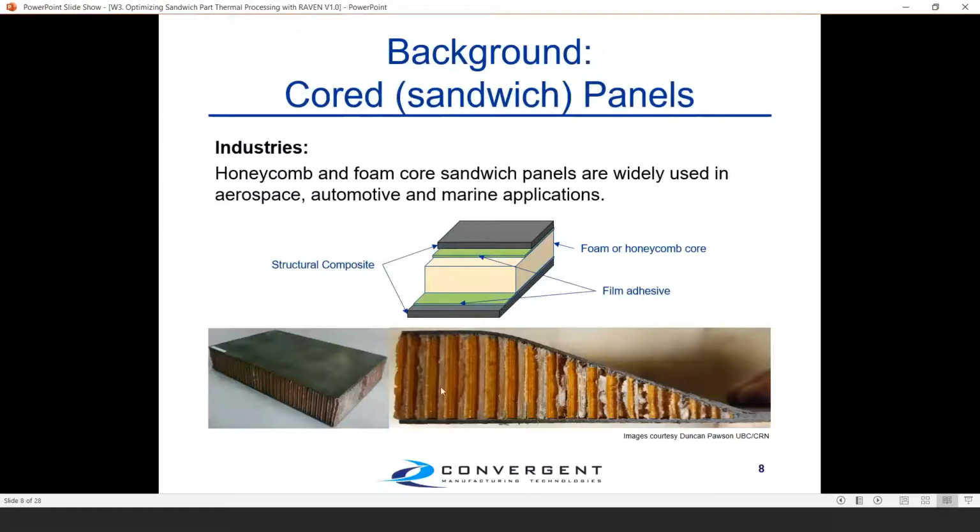It's actually one of the areas that we are assuming that we're far away from. Because the cross-section is not consistent, you can't make that simple 1D drill through, and the 1D assumptions really break down. You do actually have heat transfer and different conditions happening here. However, what we were looking at was the zone up on the top here, before that taper, and the zone down at the bottom here.